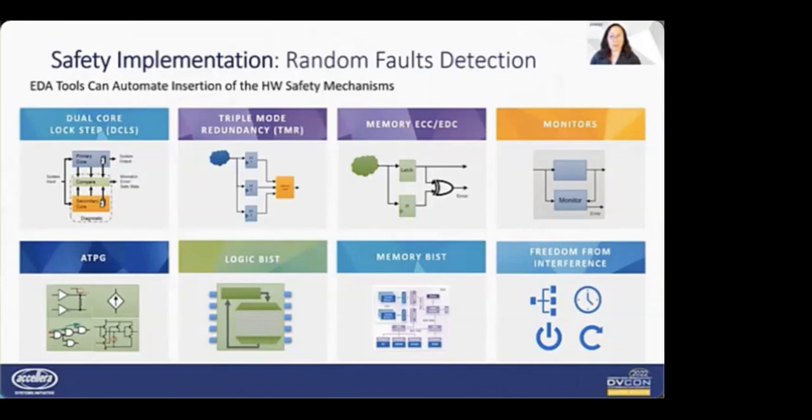We would like to also point out the usage of ATPG for achieving zero defects at manufacturing of the chip, and the BIST capability, or built-in self-test, that enables key-on or key-off testing, or even periodic testing of the design. Synopsys provides automated solutions to insertion of these safety mechanisms in the design and addresses physical requirements of the safety mechanism implementation, such as physical separation of duplicate cores and freedom from interference.